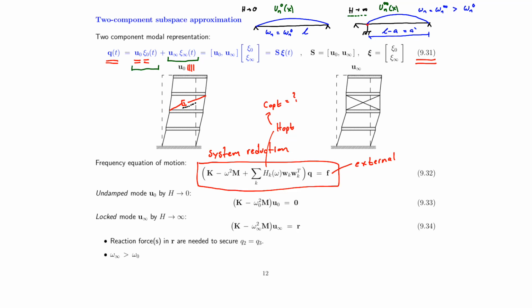So the actual vibration shape is somewhere in between these two limiting cases. If the damper is too soft, then it operates as to the left, while if it becomes too stiff, for a too large value of H, then it vibrates more like the right mode shape, with a slightly increased frequency because of a slightly reduced effective cable length.